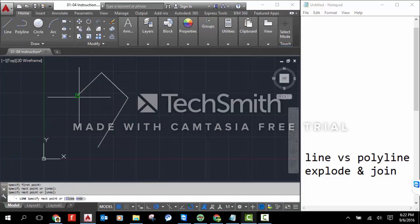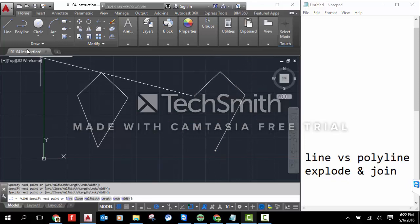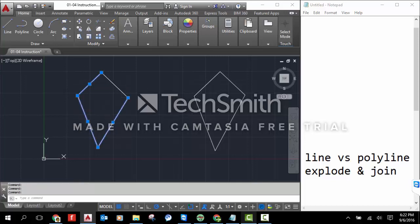just kind of close, and then I'm going to close it with the line tool, and then with the polyline I'm going to do the same thing and close it. Okay, so far just about the same. When I hover over, though, you can see this is individual parts. They're all individual pieces, and so if I grabbed this piece and I moved it, AutoCAD recognizes it as individual lines and not part of a group.